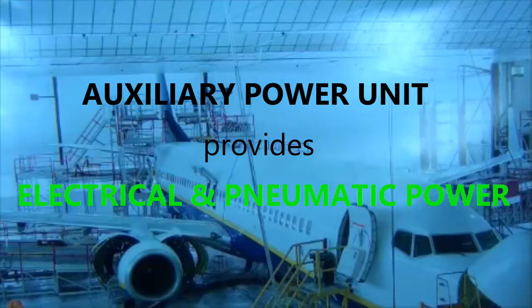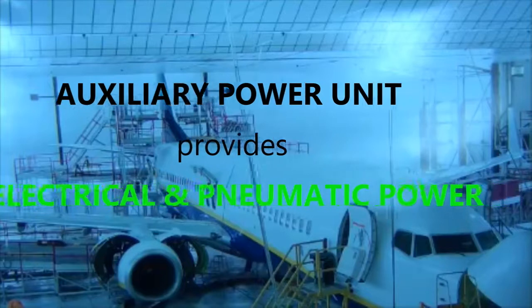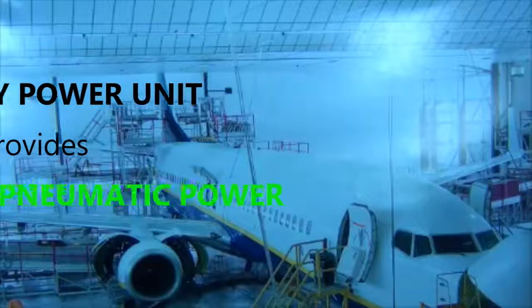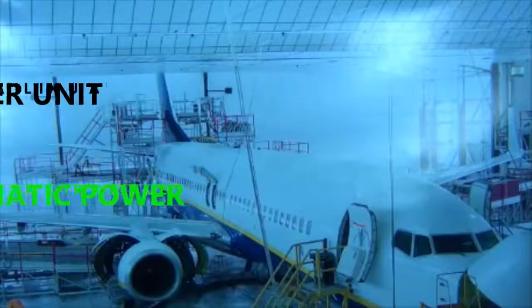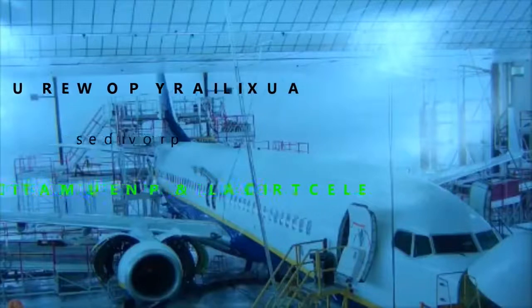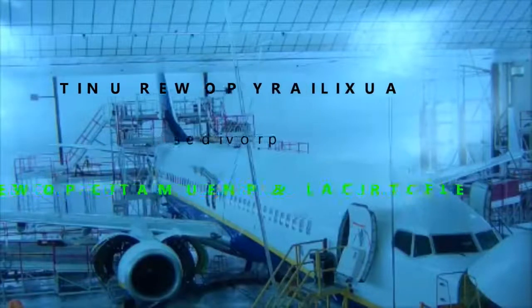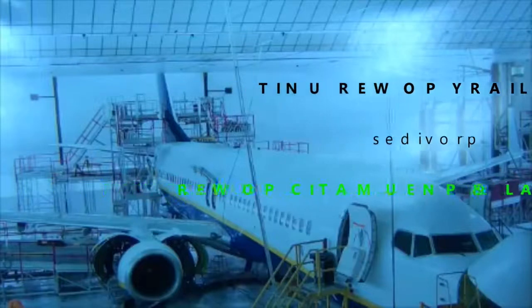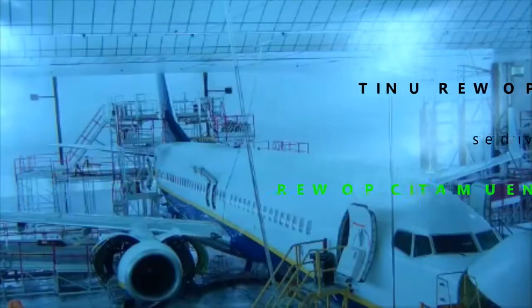All right, so you have the APU in the back. You have the electrical power and pneumatic power that have altitude limits as far as their usage. It varies, but do know this: when the pilot is using both the electrical and the pneumatic power in flight at the same time, it's only available up to 25,000 feet.